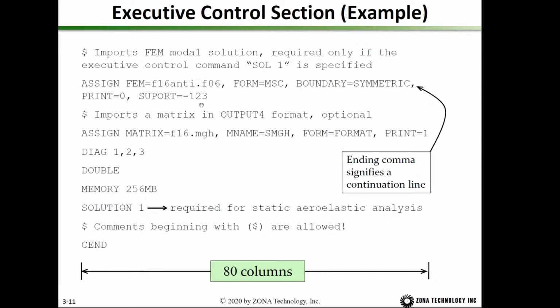This is a typical example of an executive control section. If you specify solution 1, that means you want to perform static aeroelastic analysis. In this case, you have to import the structural finite element solution using the ASSIGN FEM equals executive control command.